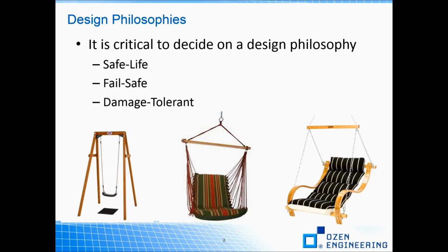The damage-tolerant philosophy, which is the last item here, can be seen as a compromise between the safe life and fail-safe design approaches. With this approach, the product is designed with some built-in redundancy such that it meets fail-safe requirements, and also it is regularly inspected for cracks such that cracked components can be serviced in time. With this approach, it is important to have information about the loading, how that loading affects crack growth, and how big a crack results in immediate collapse.